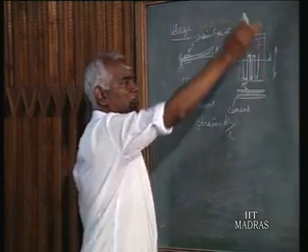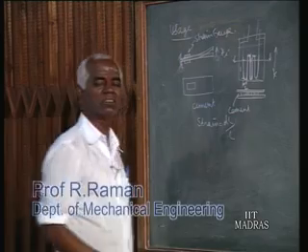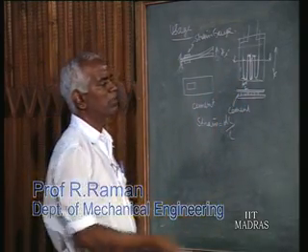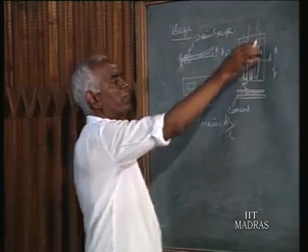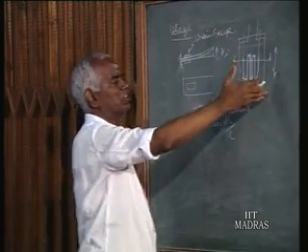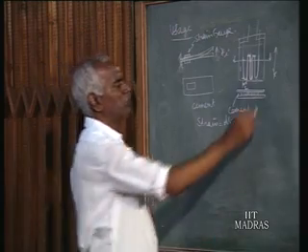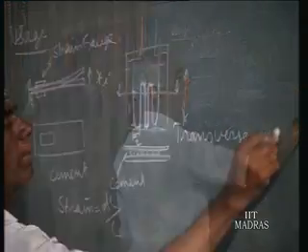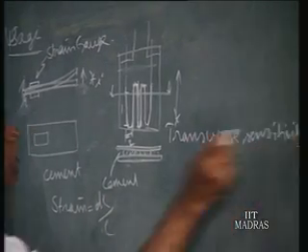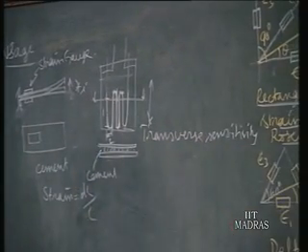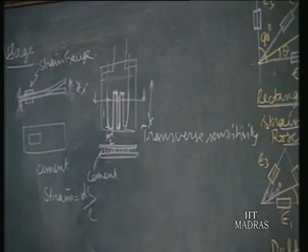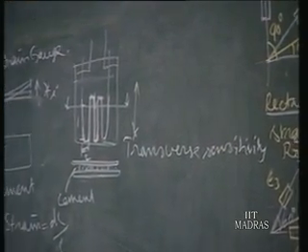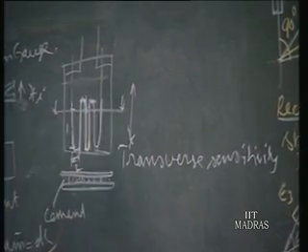So when A is increased, R is reduced. For a given axial strain, some portion of the strain gauge has reduced resistance, the major portion has increased resistance, and a smaller portion is decreased. So the net effect on the strain gauge for an axial strain is reduced. This is called transverse sensitivity. But in most strain gauges, the perpendicular segment portion of the total wire is very small, hence the transverse sensitivity will be low. So this is one of the error sources.